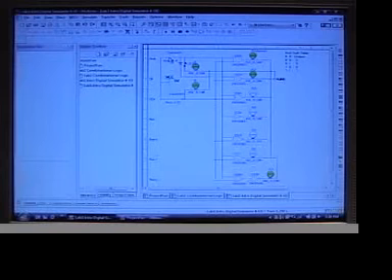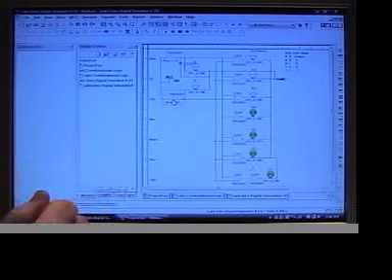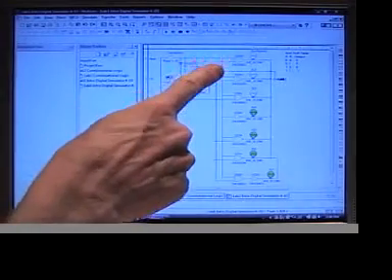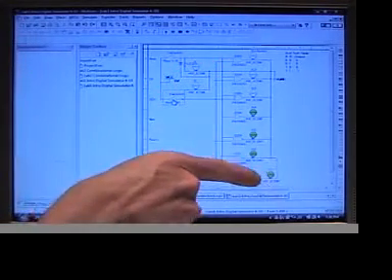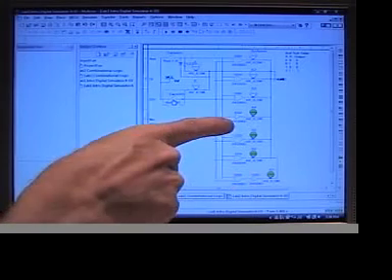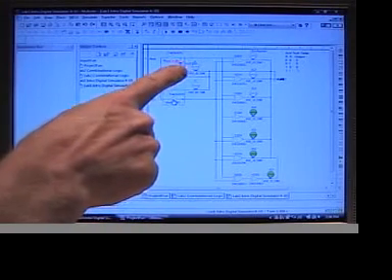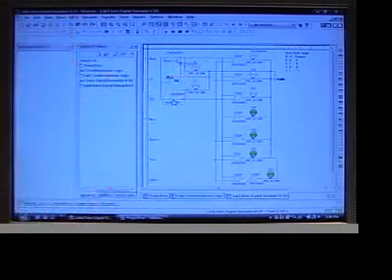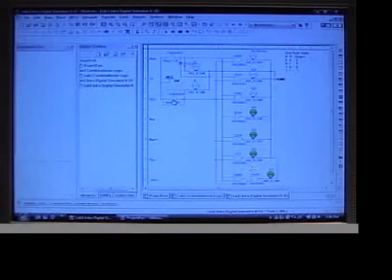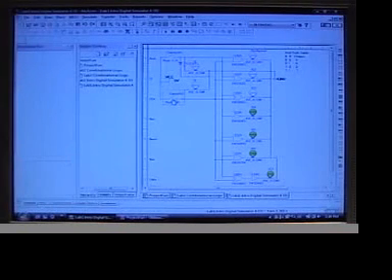And so the final switch setting to go through is to open both these switches. So I'm opening switch A and opening switch B just by clicking on them in Multisim. And now you can see again the output light bulbs correspond to the output of the device as it should be, with the two inputs as zeros. Alrighty, and that's how you use the simulate function in Multisim.